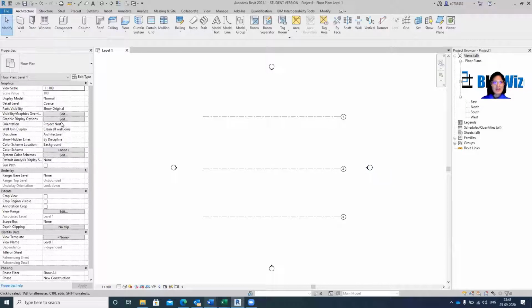Now, if I go here, right now my orientation is project north. If I go here and click true north and apply, nothing changes. Now, what is project north? Project north is something that is inside the project. For the sake of the project, I'm considering this is my north, this is my south, east, and west. But when we put coordinate systems into Revit, then it gets the actual coordinates.